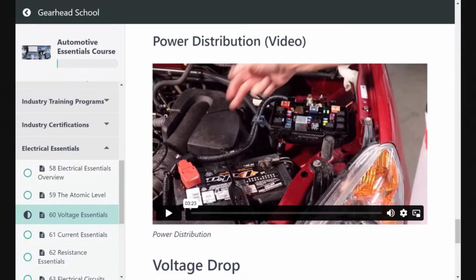And you'll see in some other lessons that I have, which again are available in the course, a tremendous amount of diagnostics can be done right there at the fuse box. I can pull these fuses out, push in fuse loops, put a current clamp on, and stand there at the fuse box and look at the current feeding the fuel pump and injectors.